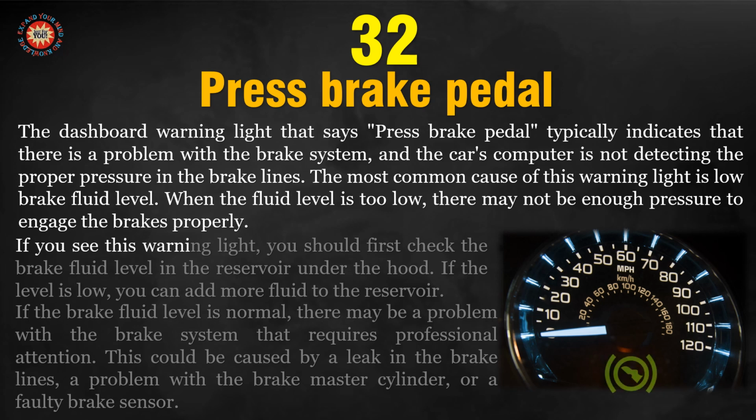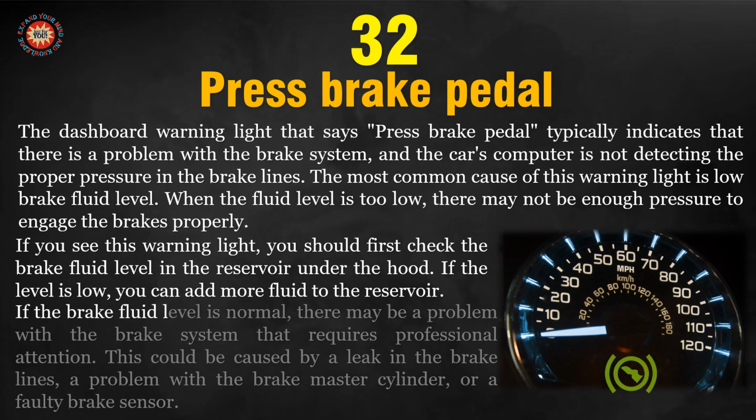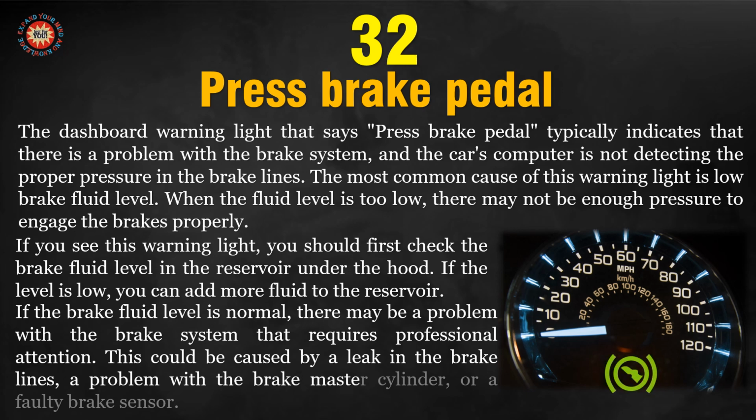If you see this warning light, you should first check the brake fluid level in the reservoir under the hood. If the level is low, you can add more fluid to the reservoir. If the brake fluid level is normal, there may be a problem with the brake system that requires professional attention. This could be caused by a leak in the brake lines, a problem with the brake master cylinder, or a faulty brake sensor.